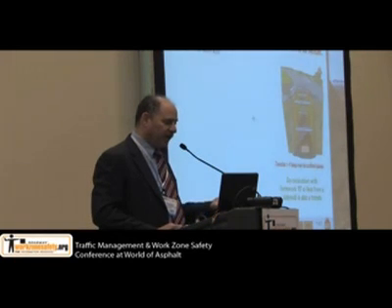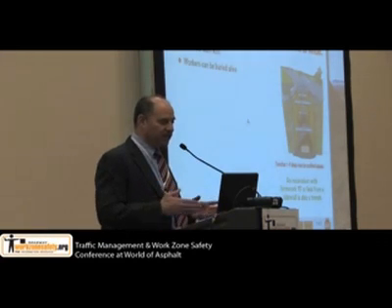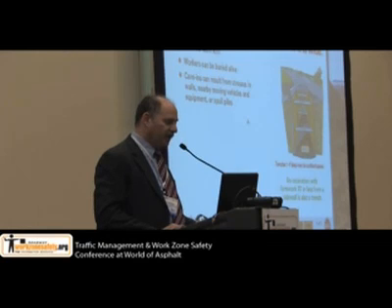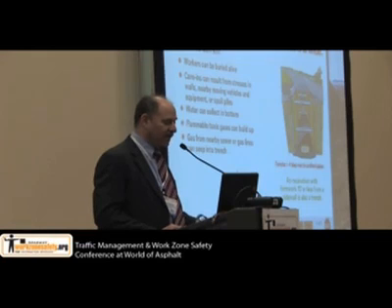First we have to really define what a trench is. It's an excavation that's deeper than it is wide, and workers can be buried alive. Cave-ins can result from stresses in the walls, nearby moving vehicles or equipment, or spoils piles. Water can collect in the bottom. You can have toxic gases or flammable gases in the bottom. Gas can come from a nearby sewer or gas line.